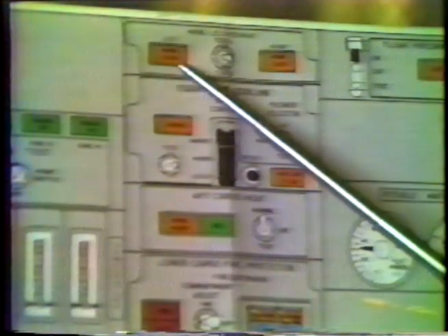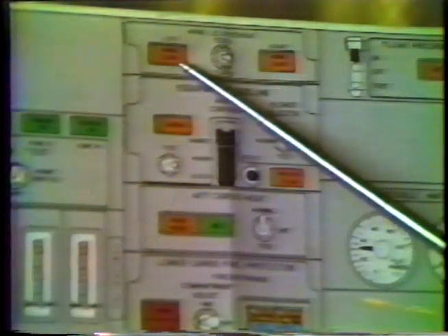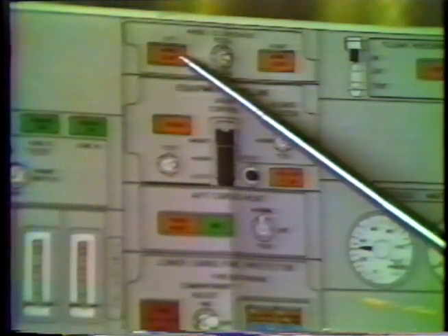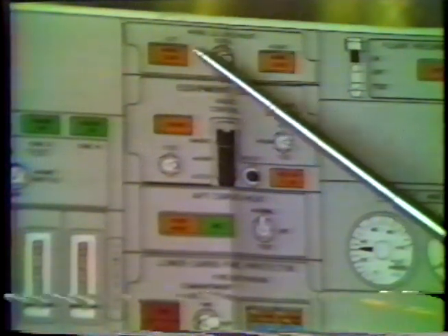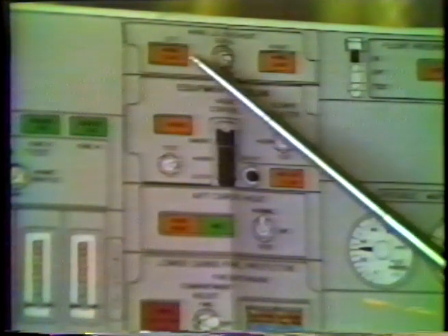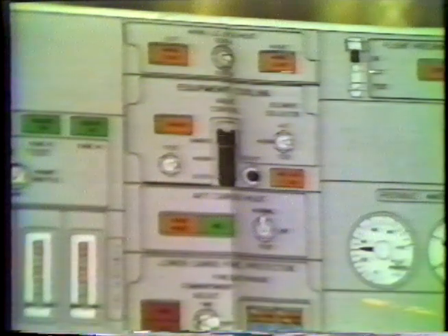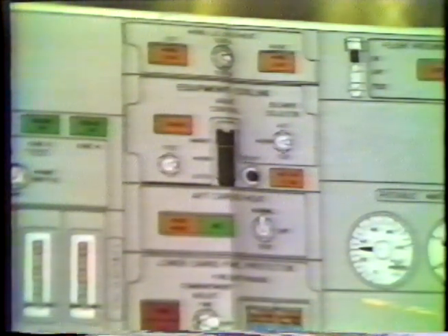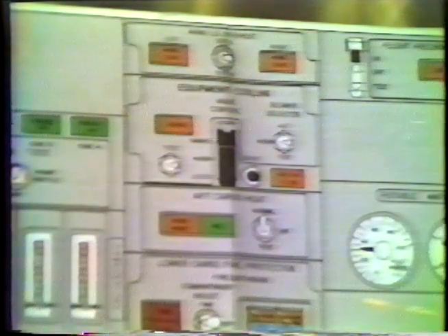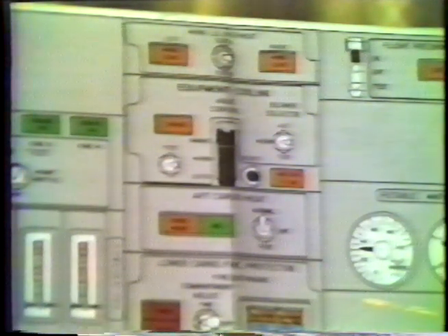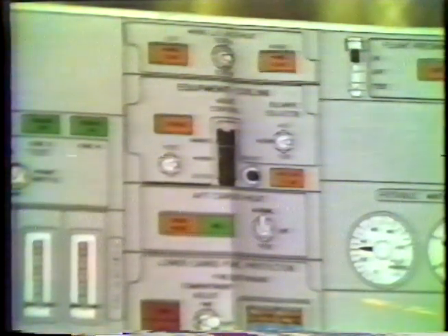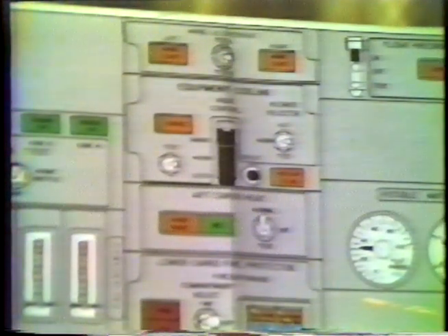Generally, if a wing overheat light comes on, say the left one, that would indicate a pneumatic leak in the left wing, and you would have to therefore isolate pneumatic air from going to the left wing by closing the isolation valve and the number 1 and number 2 bleeds. This most times would relieve any pressure and temperature in that area, and the light may go out.